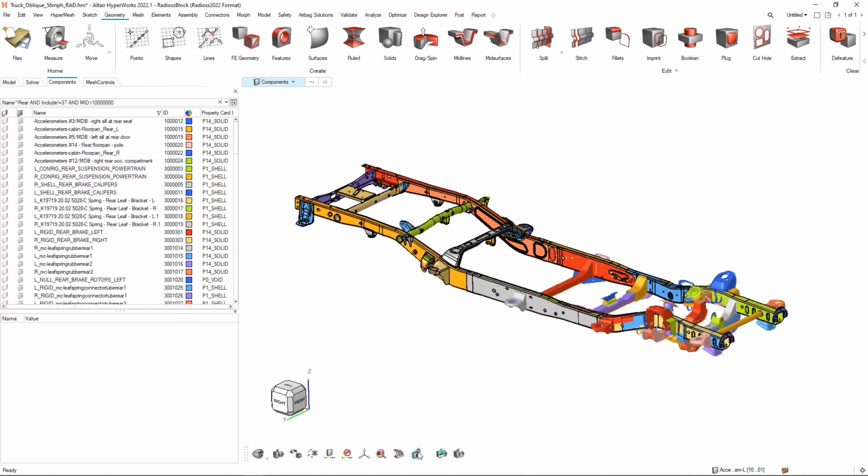So we have this lock option. What lock view does is lock and create a temporary view so that I'm only interacting from now on with what's on the screen, so the frame of the model. So any show all commands, isolate commands will be honoring the saved view. So I'm not going to get a load of components appearing that I don't want to interact with.